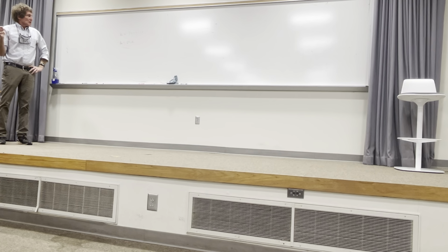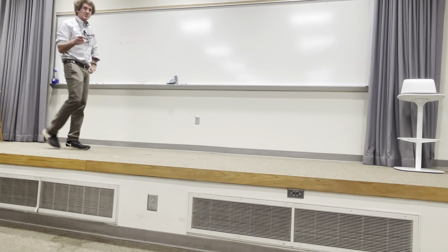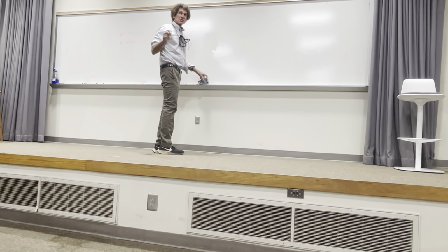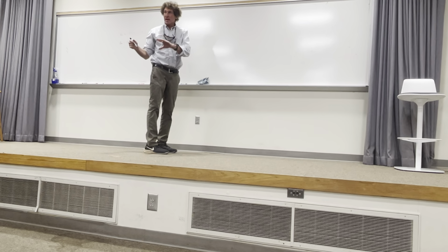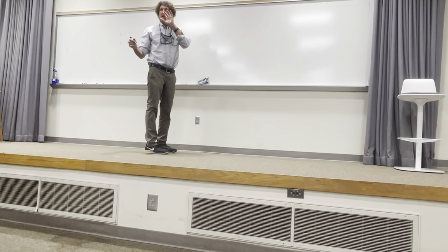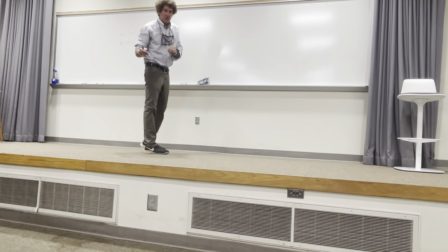Okay. We're going to do this open circuit stuff. So first thing on the Smith chart, if you have a Smith chart, it's useful to work these things with me. And this is a shunt stub, not series. It's important. Shunt implies parallel. Everybody with me? Anytime you hear shunt, we're working in the admittance domain. You all got that? Shunt, admittance. If it's anything to do with a series connection, or they'll say series connected stub, then you work in the impedance domain.